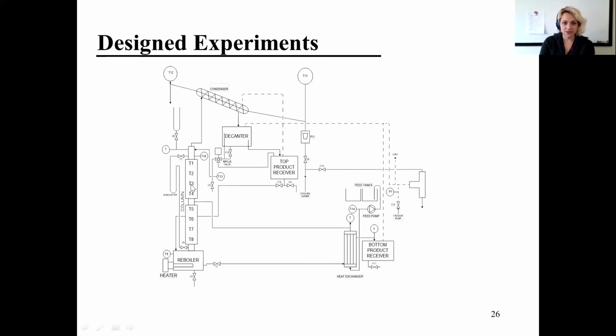So I have these trays. So this is my distillation column. Okay, I have the boiler. I'm just going to tell you quickly what's happening here. I have my feed inside my distillation column. Based on their different boiling points, I want to get some products. My boiler is going to add heat to my distillation column.